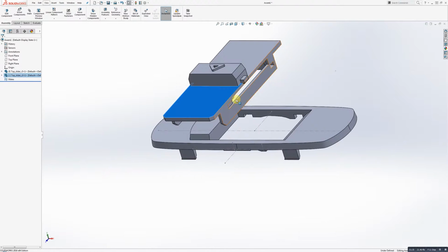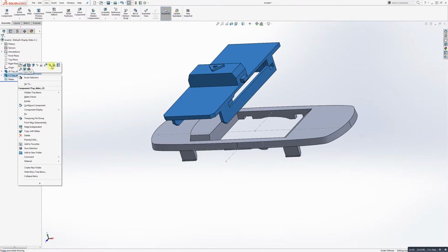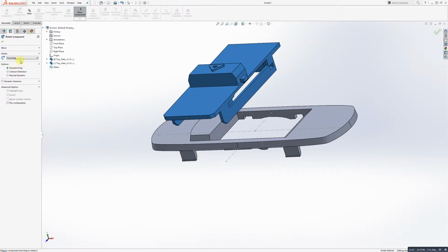So next thing I got to do is obviously I have to rotate it sideways, so I'm going to go to rotate component, and then I'm going to go to delta XYZ, and then I'm going to look down here at my little orientation jack, and I'm going to find the one that's sticking straight up through my model. So it looks like it's Y. Okay, this is a Y up model, so Y is the up down direction. That's also the direction I want to spin my model. Think about the Y as like an axis to spin around.